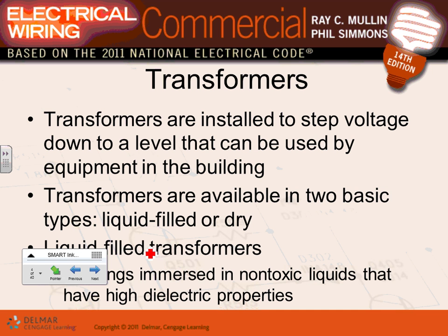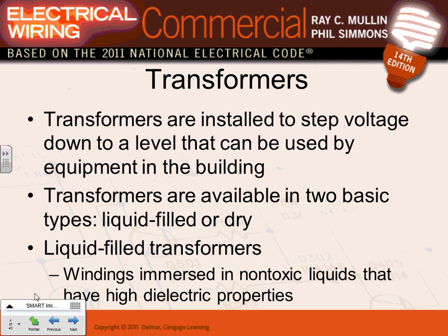So now that you saw the whole picture, the chapter is talking about different parts of it. Transformers. Everybody knows where the transformer fits in this picture. What do they do with the transformers? They step the voltage to a usable power. So like the 13.8 kV that I put on one side, step it to 480. That's their job.